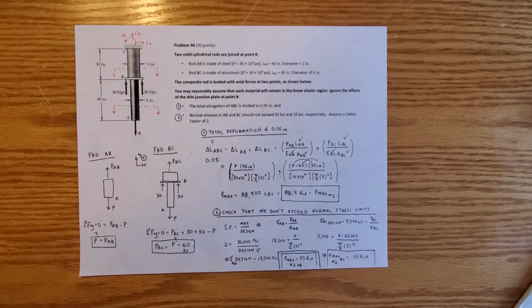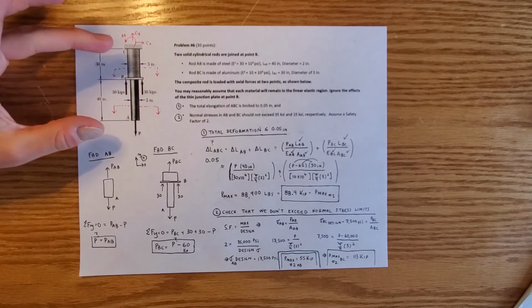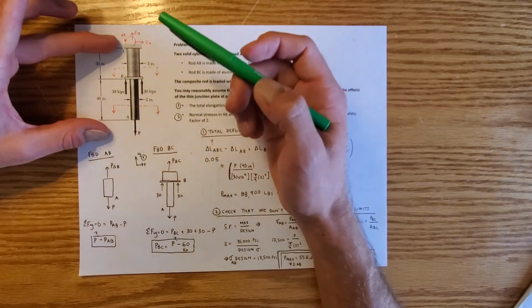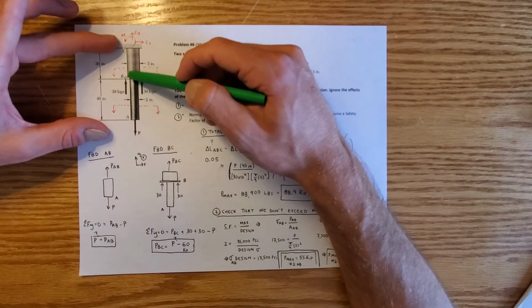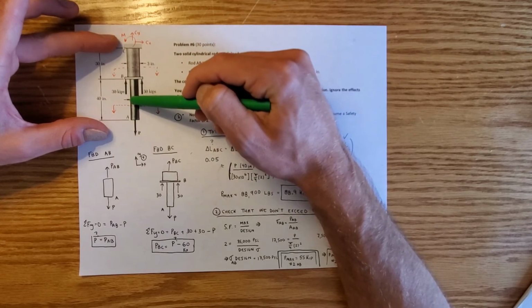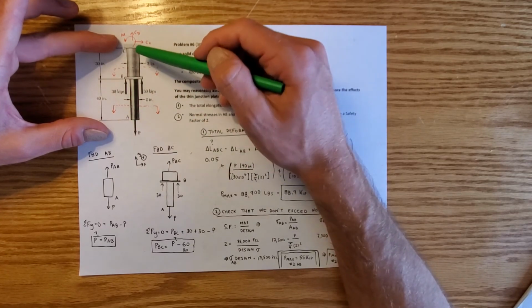And what you can see in this type of problem is for a rod, just to reiterate, the steps you take are make a cut through each section of rod, or sometimes there'll be forces inside here. Like for example, there could be a force right there. You would want to take a cut through here and here if the force was inside of AB. But you'll take cuts through at least every lettered section.